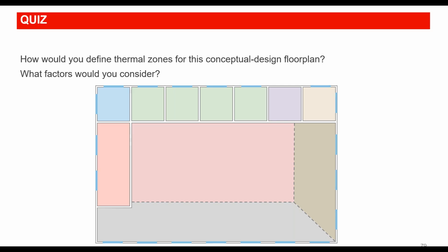You're using a lot of assumptions, likely from energy code or existing building information that you have or previous project experience. You're probably filling in a lot of gaps and making a lot of assumptions. So keeping track of your data that you're using in the model is very important at this stage. Particularly when you get to the next stage, like say you go from concept to schematic or design development, and some of your input assumptions change, you'll need to be able to document why the results of the model have changed. And if you have your assumptions documented really well, it's really easy to show, maybe the occupant density changed or the programming changed, and that's why the model results changed.